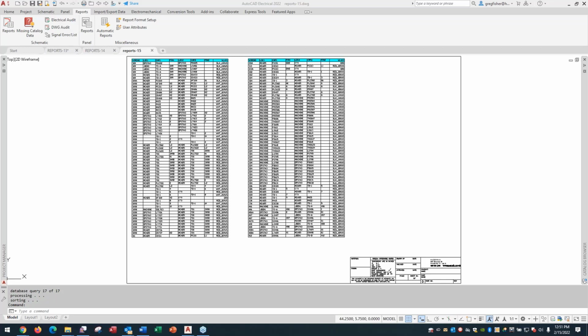I do a panel report. I use full include schematic, not referenced on panel, purchase list. After I run the report and select all the fields that I want included in the report, I save this as a new set file. Then I use this report that I've saved, and the full include schematic and display and tally purchased are no longer checked.